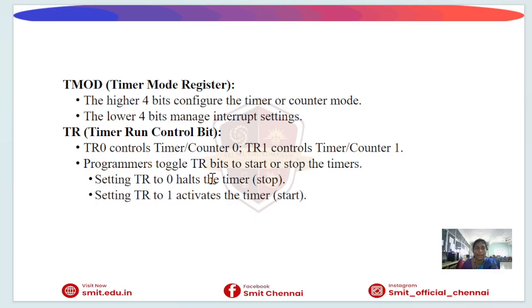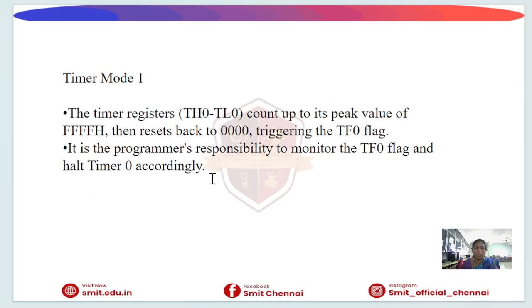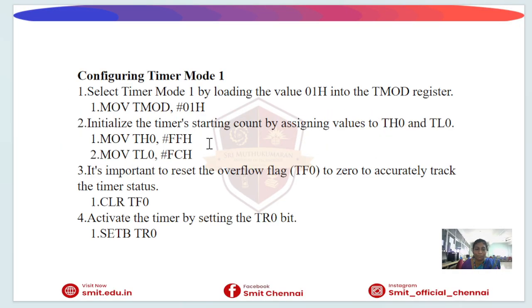Then timer mode 1. This mode is a 16-bit register, from 0x0000 up to 0xFFFF. The timer counts from the loaded value up to FFFFH, so the maximum count is 65536. This mode is widely used because it provides long delays.